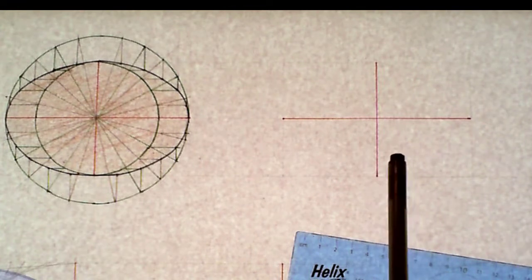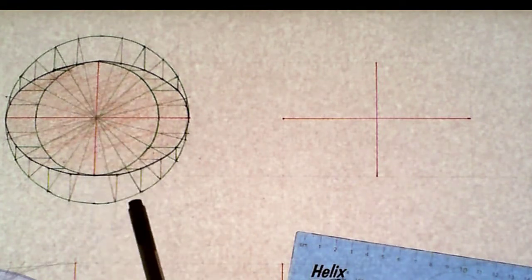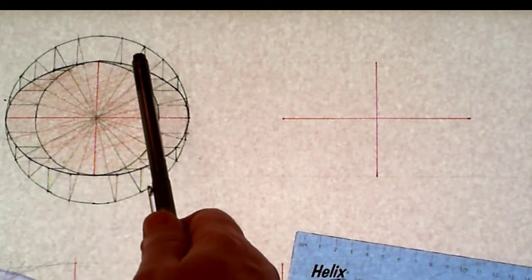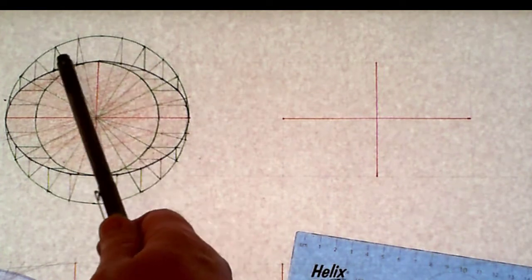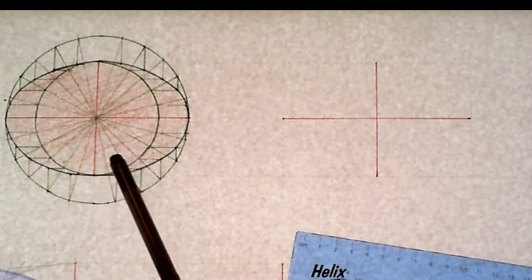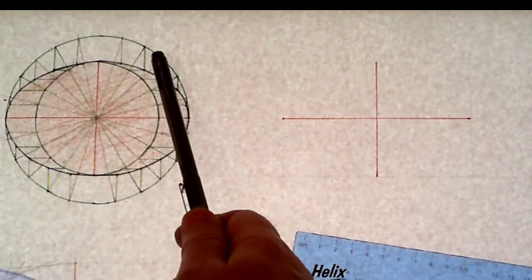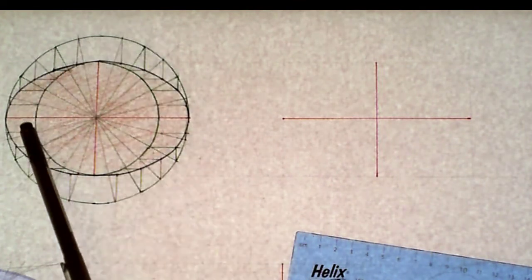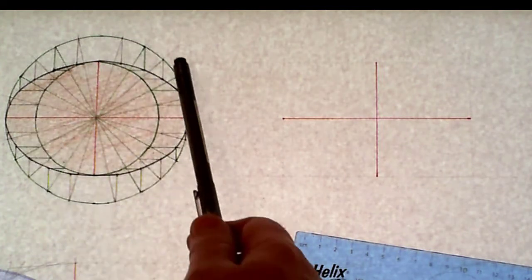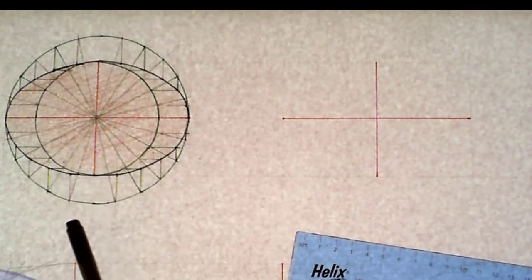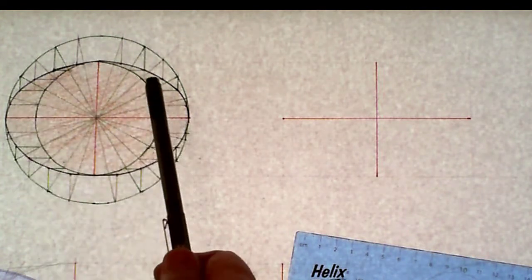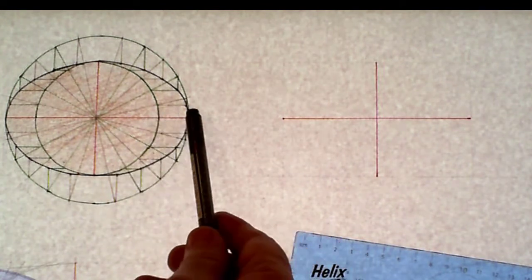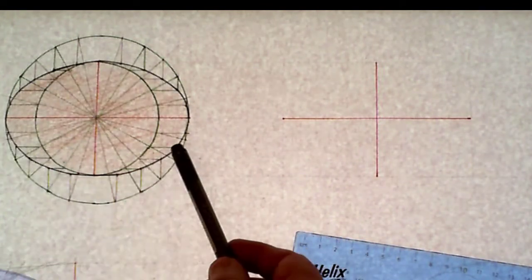But before I go on to the next one, I'm just going to remind you about the particular lines I've drawn in here. A lot of the lines drawn with the ink pens, the green and the red and so forth, are quite hard, so a lot of these are just going to be construction lines. When you're drawing them, these construction lines should be light. I'm only darkening them in for videoing purposes. So try and keep the construction lines light, and all you want to be heavy when you're drawing it in is the actual ellipse itself.